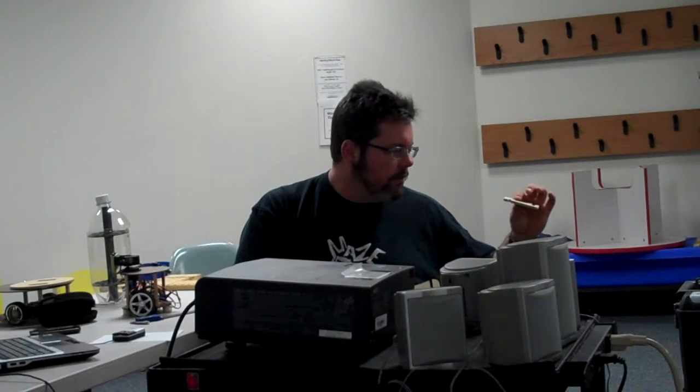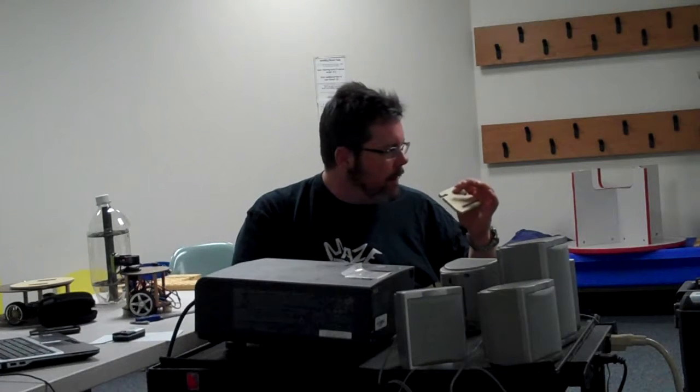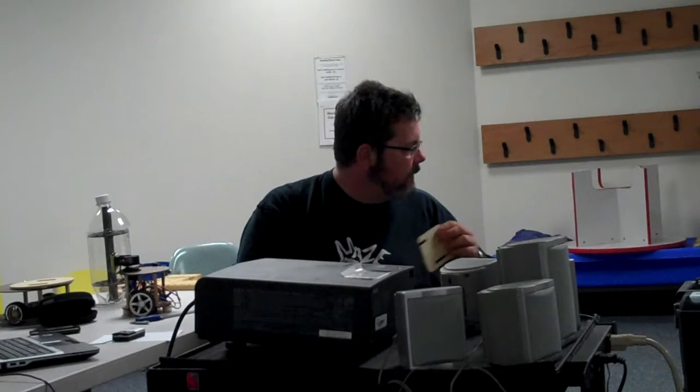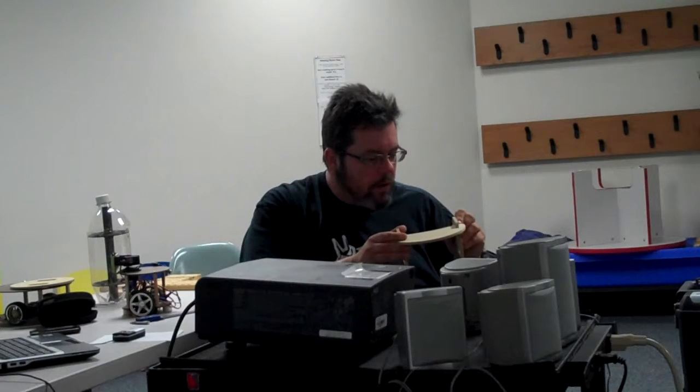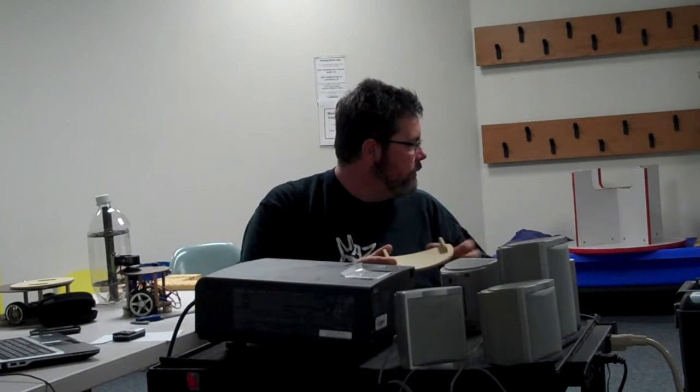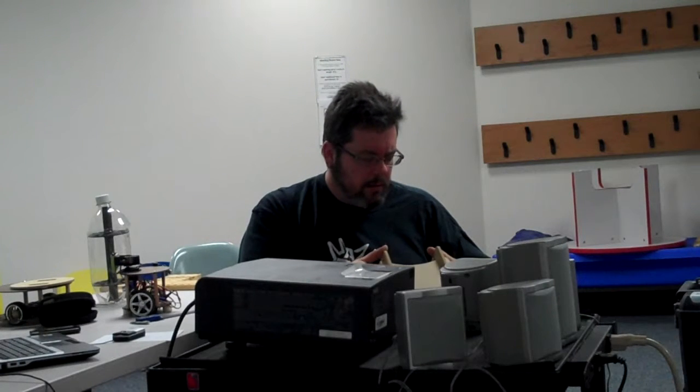Even if you get a sheet of this 4x8 from Lowe's and go back a week later, it's going to be slightly off. For building a wall, no one's ever going to know. But with your calipers, it might be just a thousandth of an inch off, and then your part that was really tight is now a little loose. So you always got to remeasure the wood that you get. Just keep a process.